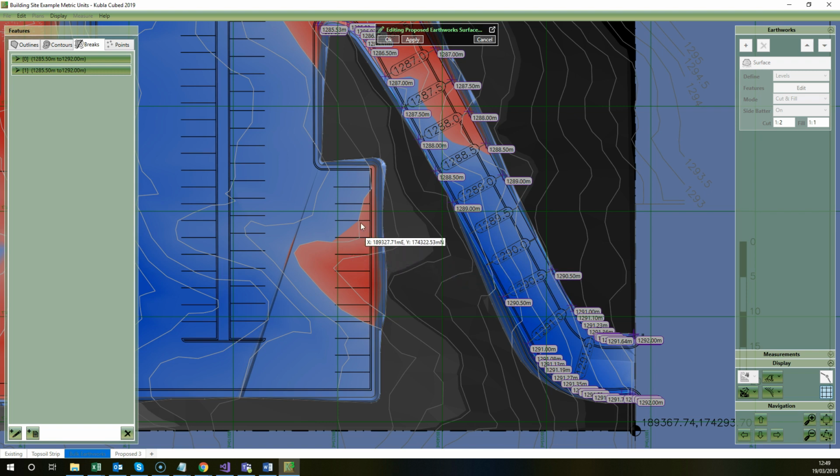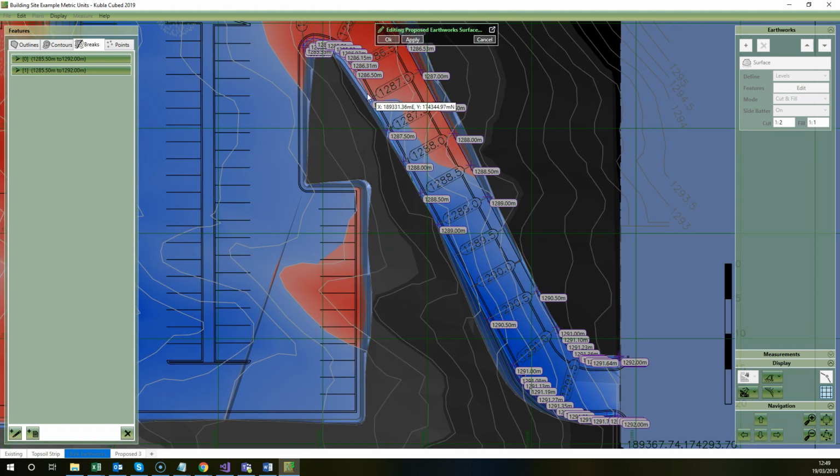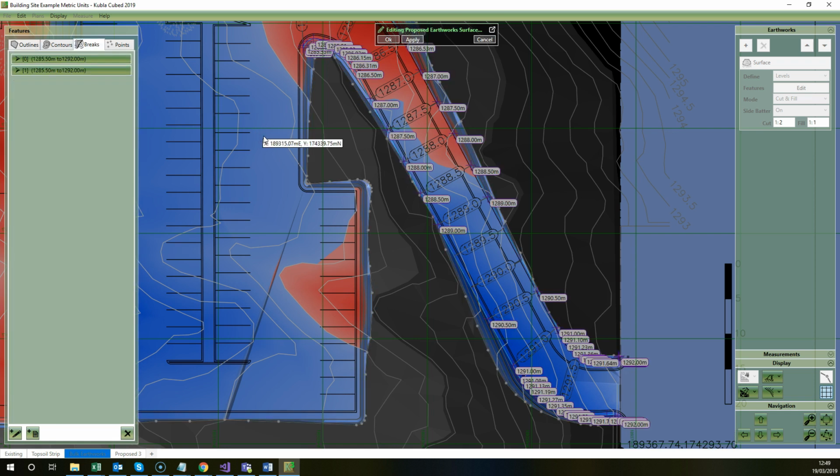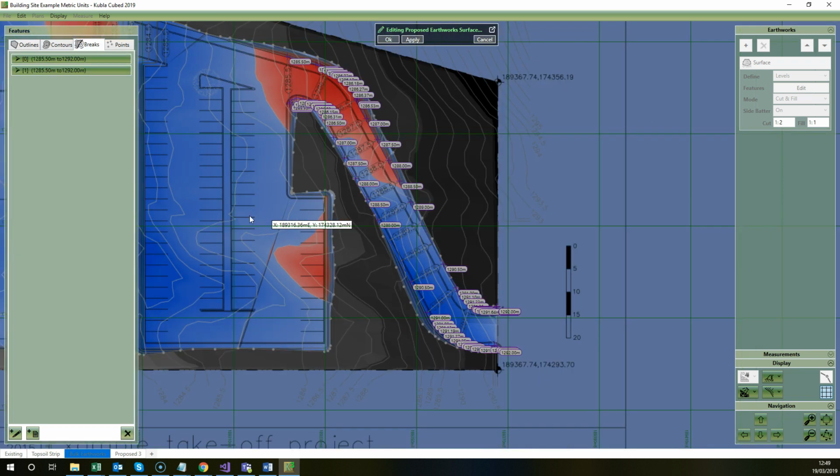So instead, we've made a slight improvement to that, is that you can now permanently leave a value blank in a break line or in an outline which you've set to enter the values explicitly, which is a similar sort of thing. So break lines are quite useful for retaining walls and hard edges, etc., or the side of roads.